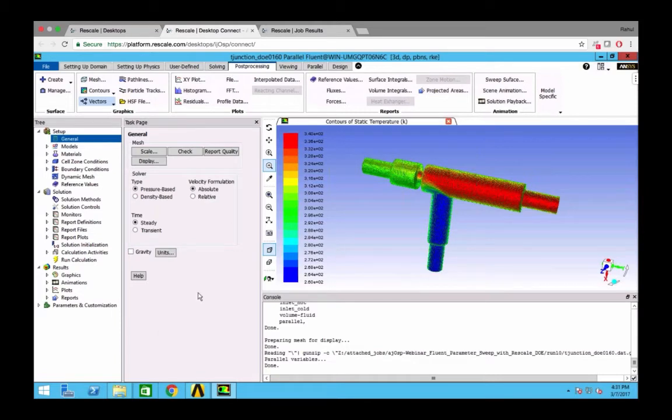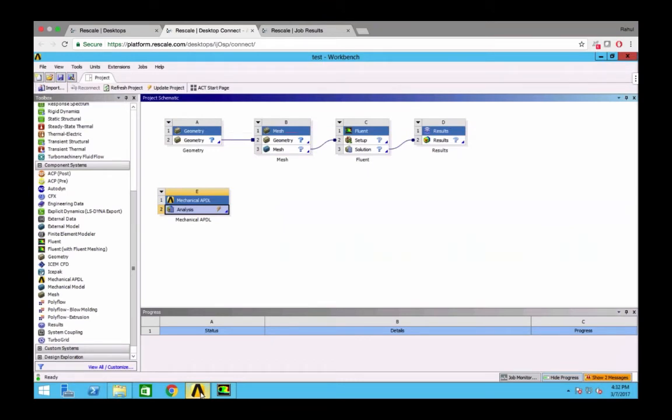job. So for some of you who are not too familiar with the batch environment, you can also use Workbench. It's supported on our remote desktops. And once you launch Workbench, you can see your typical workflow or your setup for your jobs. And what you can actually do is use Rescale to power your simulations by using the Remote Solve Manager. You can set up your entire workflow and the job on the cloud or on our remote desktops, and get the simulation to run on our Remote Solve Manager on Rescale. Sorry. So let's go ahead and give you a demo of that.